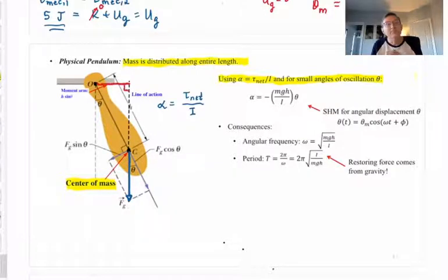There's the moment arm. So to get the torque, starting with the magnitude, I take the magnitude of F grav, mg, times the length of the moment arm, the length of that red line. How long is that? Well, I do need to know two things. What's the angle theta? And what is the distance, in a straight line, from the pivot point O out to where the center of mass is?